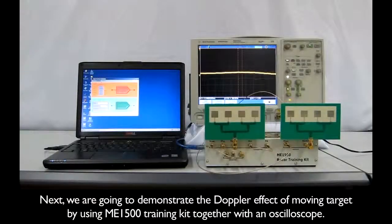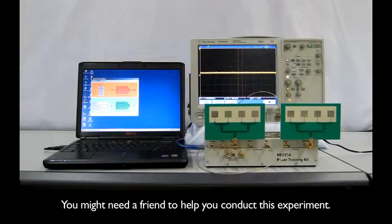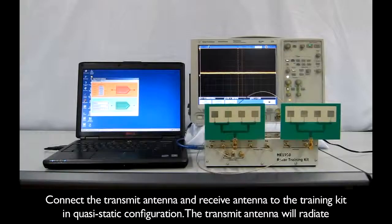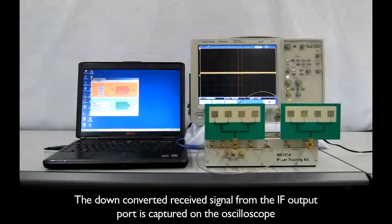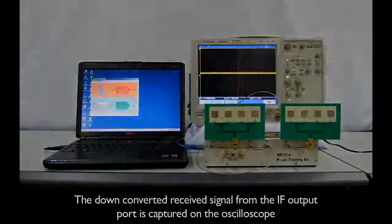Next, we are going to demonstrate the Doppler effect of a moving target by using the ME1500 training kit together with an oscilloscope. You might need a friend to help you conduct this experiment. Connect the transmit antenna and receive antenna to the training kit in quasi-static configuration. The transmit antenna will radiate the electromagnetic signal to the target, and the reflected signal will be received by the receive antenna. The down-converted received signal from the IF output port is captured on the oscilloscope.